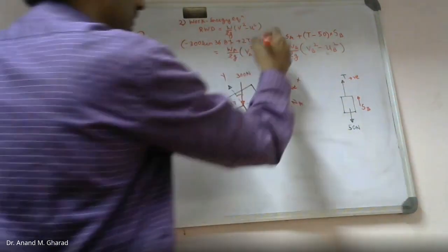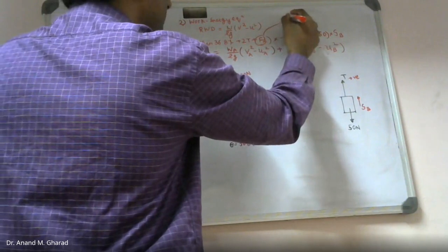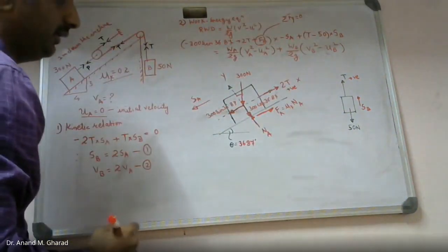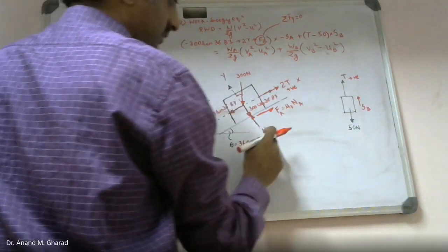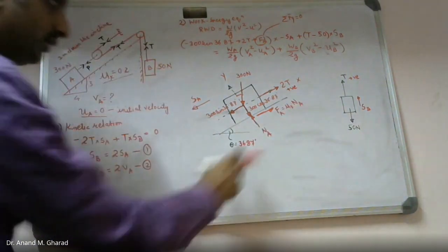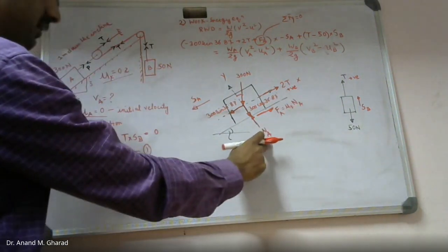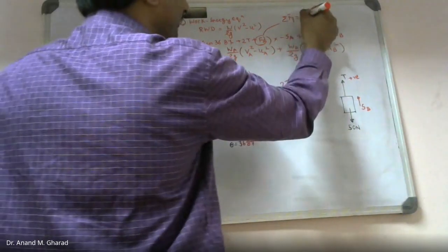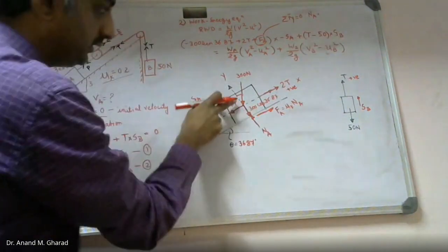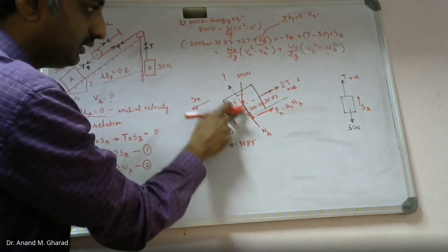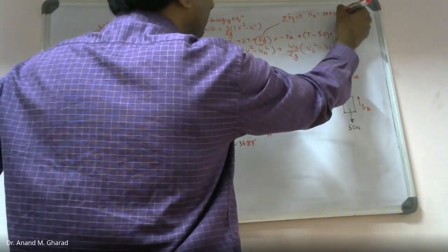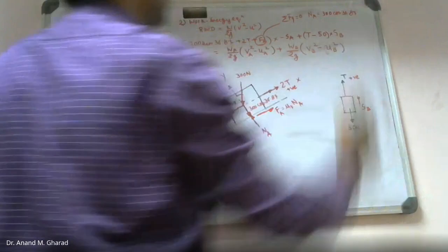FA can be easily identified by using summation of forces in y direction equal to 0. Okay. See, because this FA consists of mu k times NA value, and we are supposed to identify this NA before finding out FA. So from here what I will get is NA is equal to, there is only the vertical component, other than this there is nothing, 300 cos of 36.87.